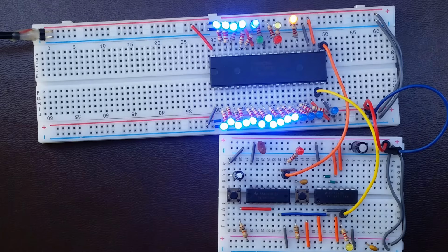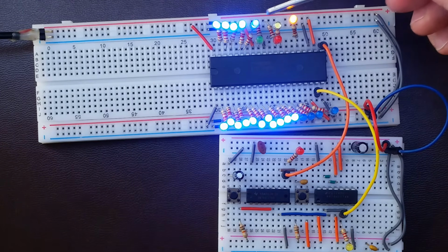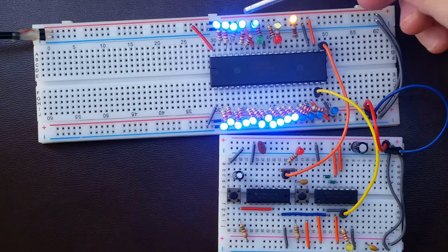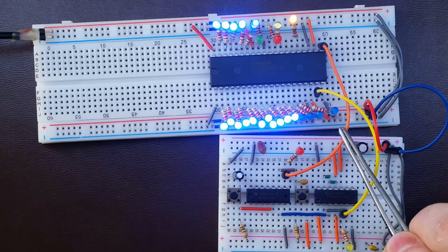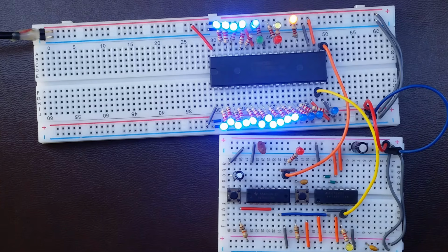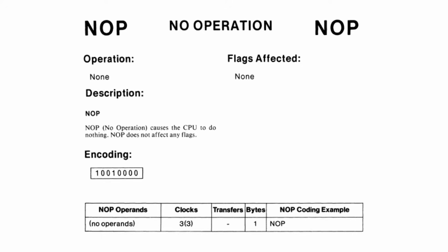We saw the processor addressing the memory in order to fetch the first byte of the program after reset, but currently we have no memory which would return it to the CPU, so the outcome would be unpredictable. What we could do is to use one machine code called NOP, or no operation, which, according to its name, does nothing, still being a valid instruction.